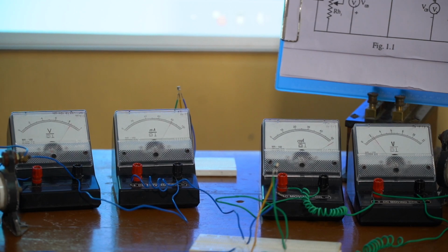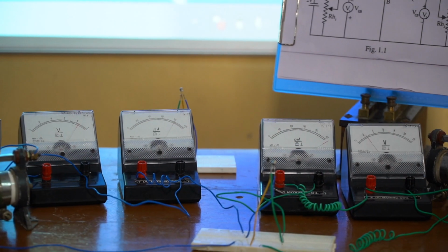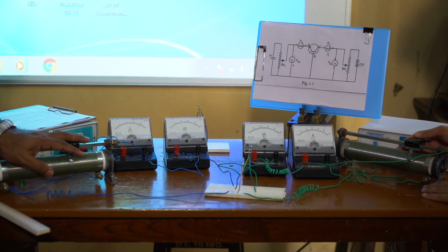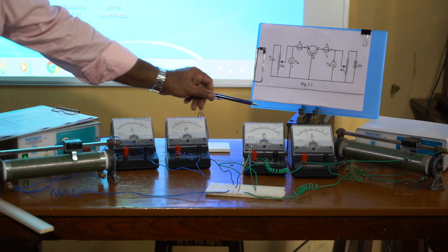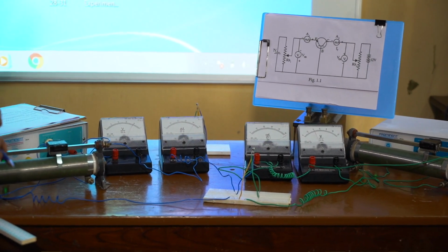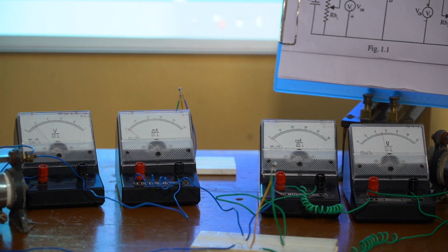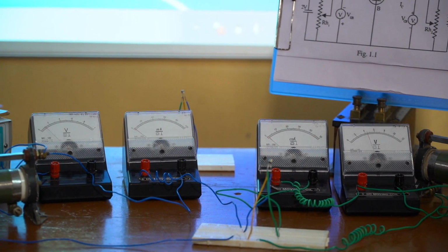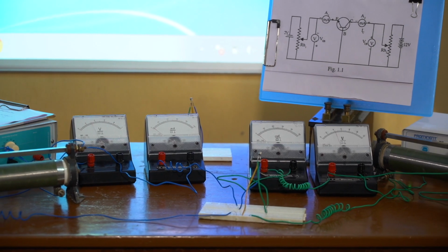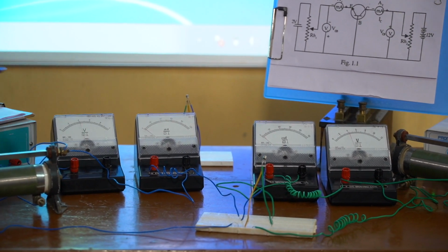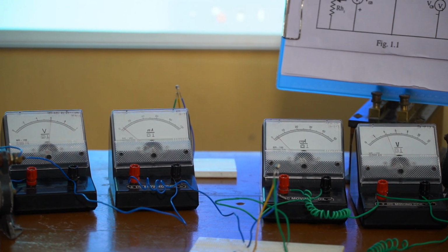Now we can repeat. Now we are changing the value of VCB. Now change the value of VCB to a value of say 4 volt. Now VCB is changed to a value of 4 volt. So we have to maintain that VCB at 4 volt. Now again we are changing the input side. We are starting with 0.1 volt. Again IE is equal to 0. For 0.2, IE is equal to 0. Say 0.4, IE is equal to 0. Say 0.5, IE is again 0.